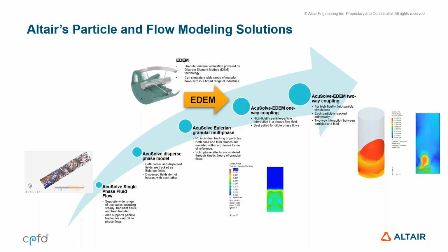One such approach is AcuSolve EDEM one-way coupling, where we still resolve all the particle contacts and particle-equipment contacts, and we take into account the effect of fluid on the particle phase flow, but the effect of the particles is not realized on the fluid. This is really suited for dilute phase flows and quick design iterations, in order to concentrate more on the solid phase flow rather than the interaction between the two phases.